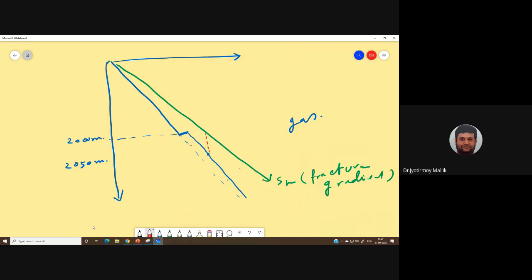So you can see my pore pressure now, at this space, the drilling window is further reduced, because the gas will have a gradient of around 0.2 bar per 10 meter. So this is further reduced.